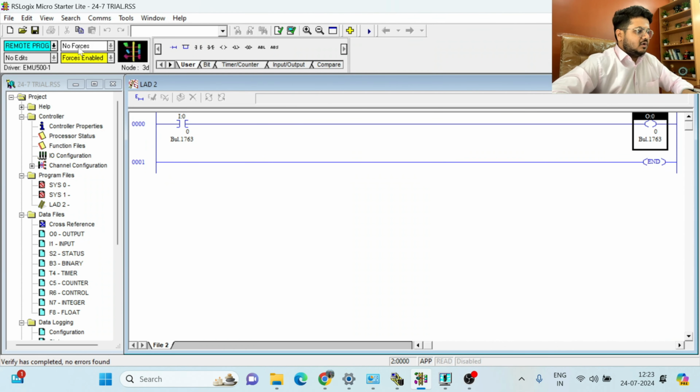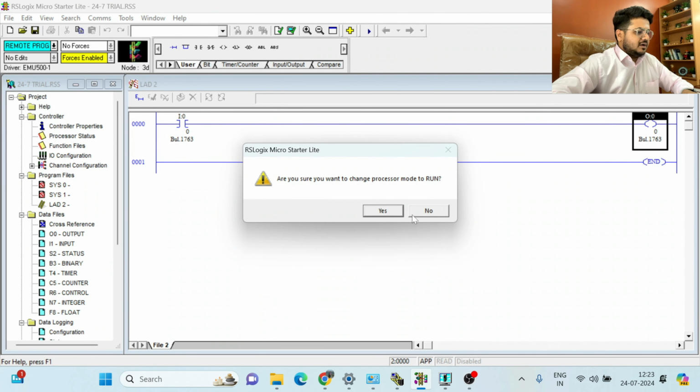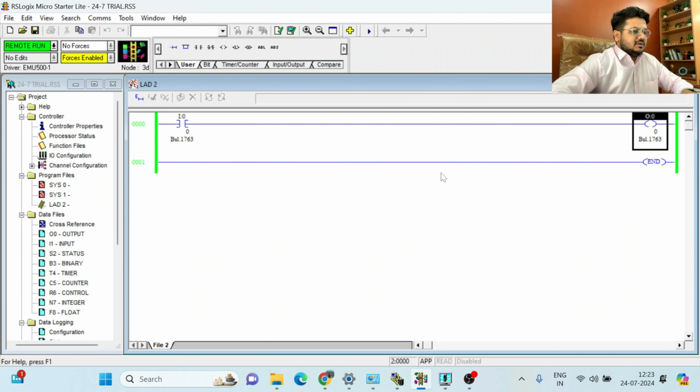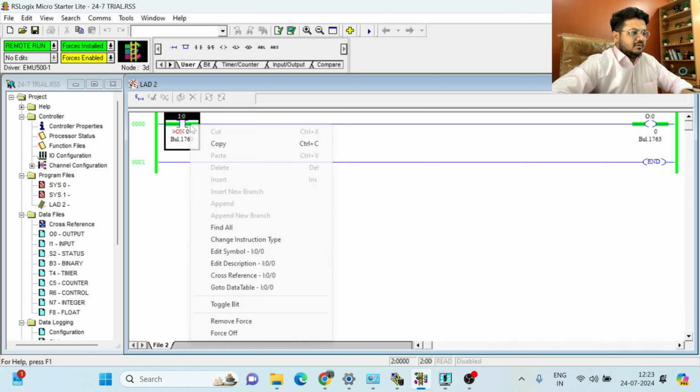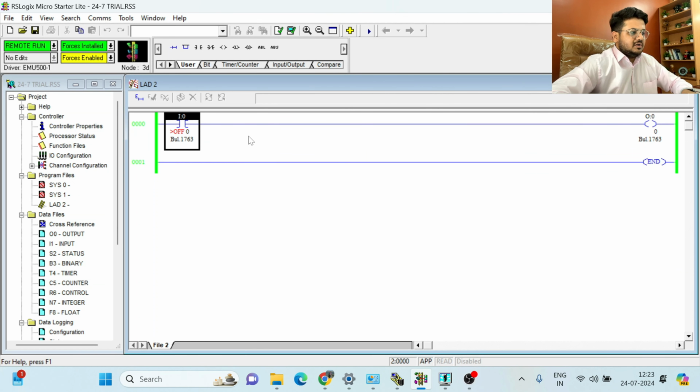After pressing all the yes, on the left side here you need to click on run. Now see, even if you do not have any physical PLC, you are online with the emulator software. If you check force on, or force off buttons here, if your input is on, output is on; output is off, output is off. This is how the emulator software works.